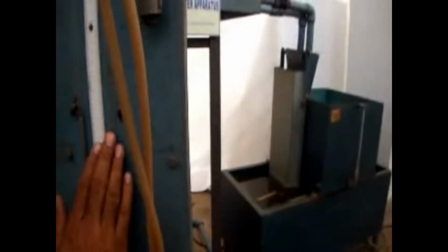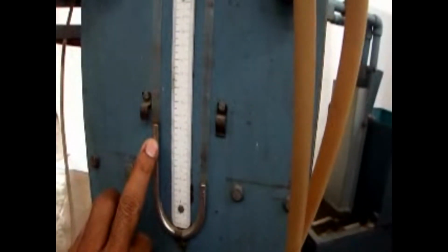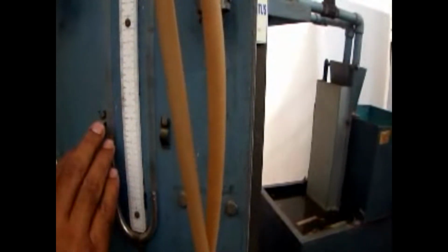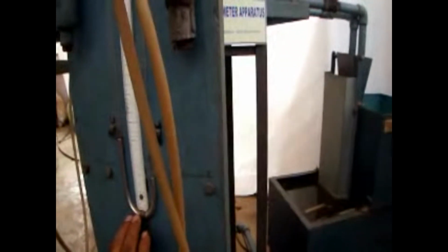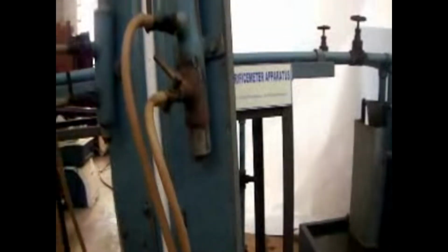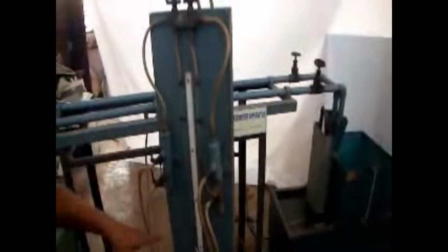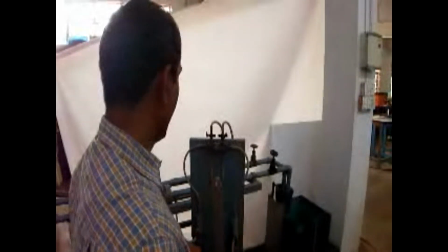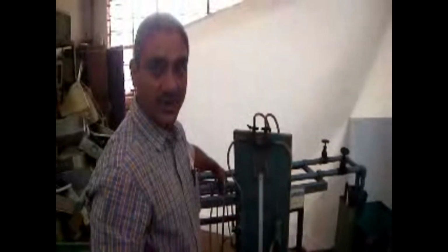So this is connected from outside, this is the outside connected limb, and this is the inflow connecting limb. So it has more pressure. Usually you will see when it is running, high pressure this side, it will go down and the low pressure side will go up. So you can see these arrangements. U-tube manometer you have already learned. So in this arrangement we can find out what is the pressure difference and what is the head that is discharging per unit time, and we can find out the coefficient of discharge by using the same relationship.